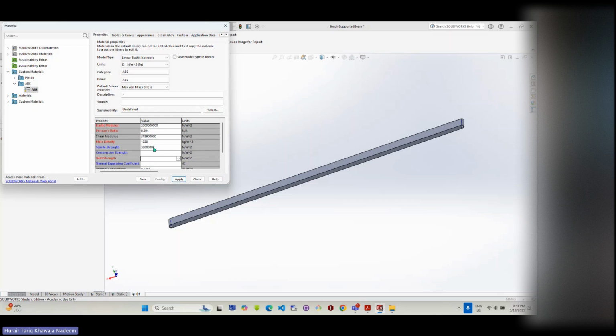But if you do not define elastic modulus and Poisson ratio, there is going to be an error because these are required in doing the calculations. So these two items are mandatory. If, for example, the values are not there or you are choosing a new material, you are going to come to the internet and search for the best value. Or you can get the values from research papers. Get the value from the research articles and place it over here. So if a material is not here, you are going to apply it from this side.